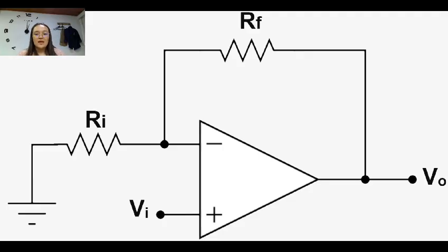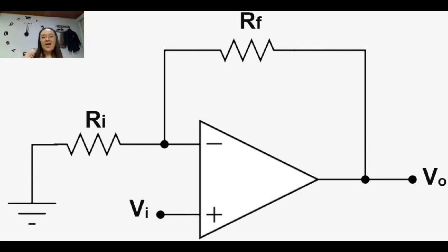Non-inverting configuration. Elements: resistor R1, resistor R2, input signal source and the op-amp. The input signal is connected directly to the non-inverting input of the op-amp, the positive one, and resistor R1 connects to the inverting, negative input. Another resistor, R2, connects the inverting negative input to ground.